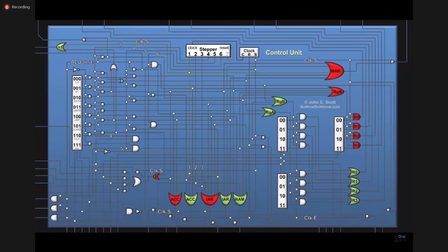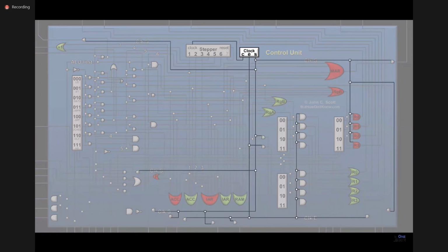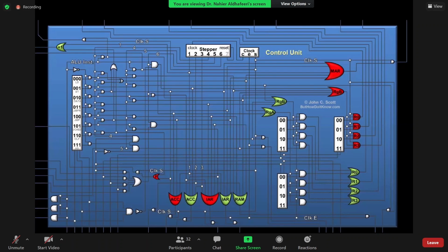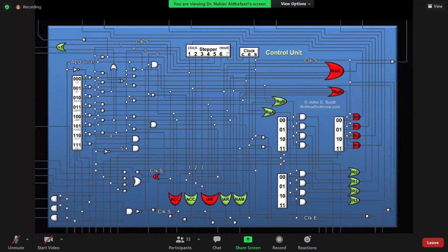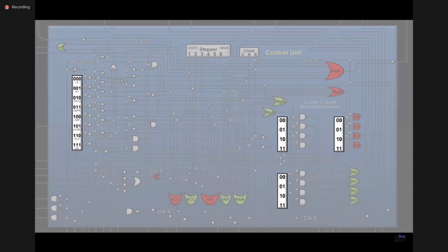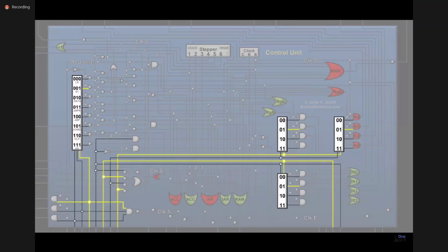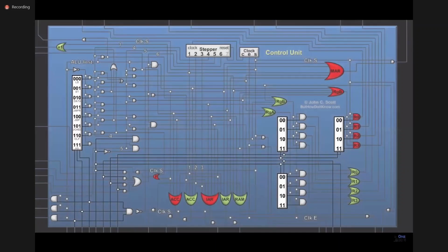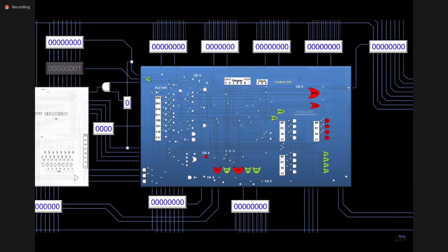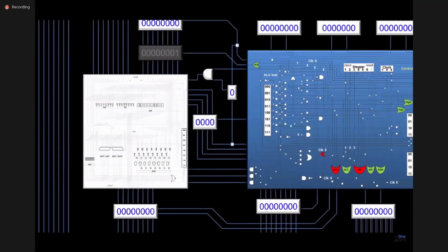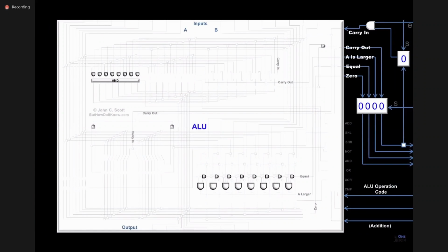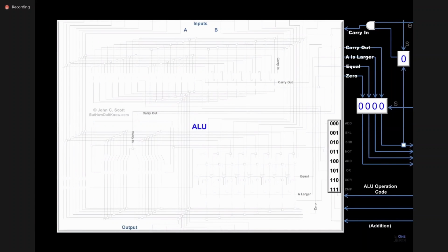This input wire comes from another small component called the clock, where the output wires turn on and off again very quickly in a steady pattern. The only other component used in this part of the CPU is the selector formed from another combination of AND, OR, and NOT gates that turn on one of several output wires depending upon what input wires are on at the moment. In another area of the CPU is the arithmetic logic unit, which includes more AND, OR, and NOT gates, along with the selector component that we just saw.